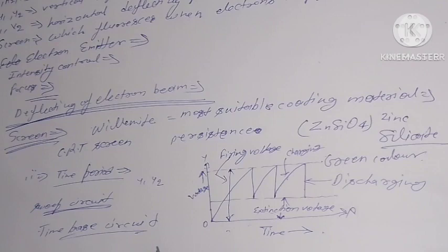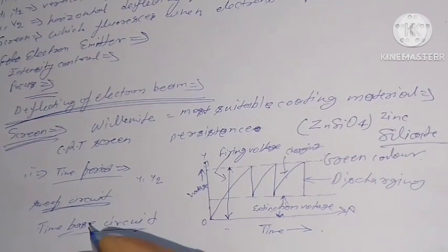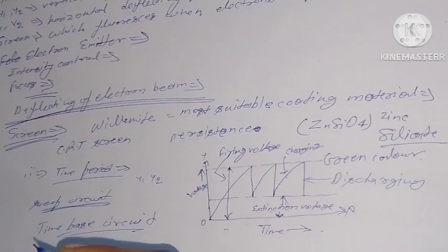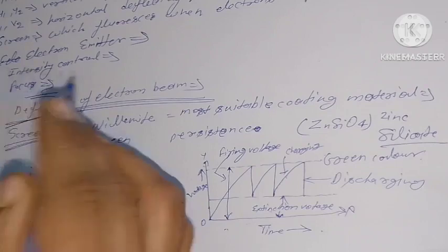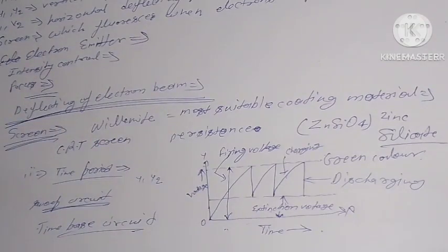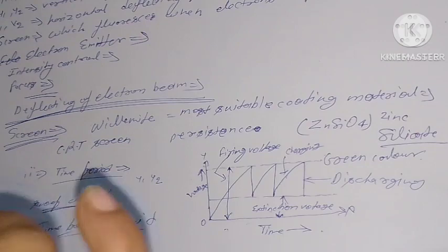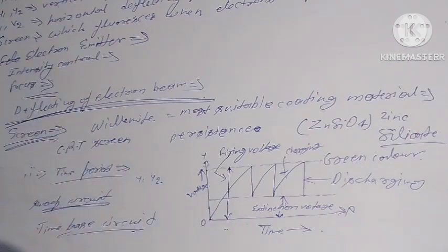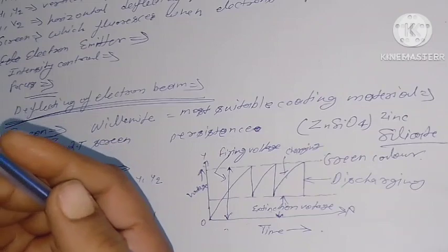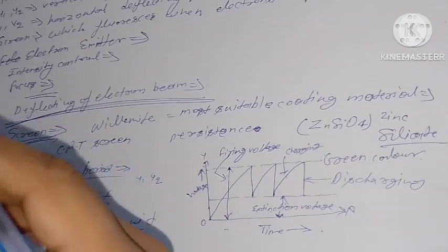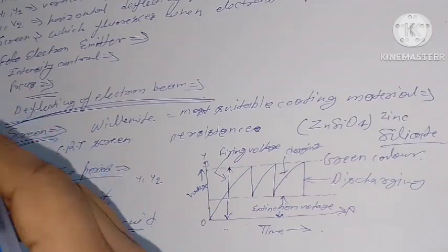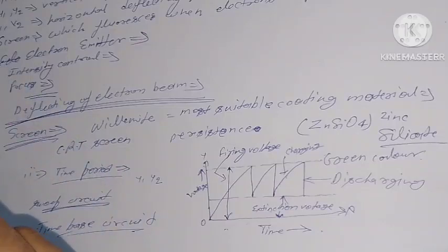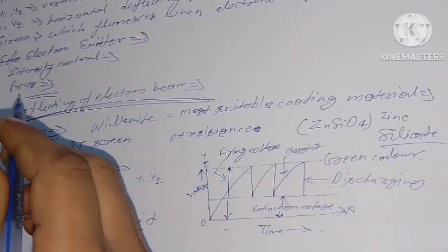The name time base is due to the fact that when a sawtooth wave is applied to the horizontal deflection plates, the x-axis on the screen may be taken to represent time. A time base is said to be linear if it produces a uniform movement of the spot. The sweep circuit or time base enables us to obtain a pattern on the screen which is exactly the same as a curve of varying voltage applied across the vertical deflecting plates Y1, Y2 as a function of time.